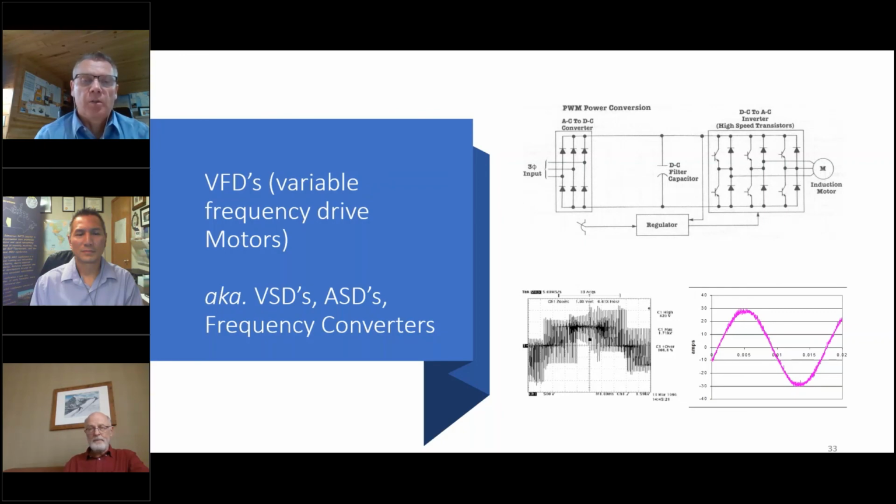And when you energize a motor, it's going to lift up from its stationary position and find its optimal place where it's magnetically happy. And on most motors that I'm aware of, in initial setup, there should be an indicator on the driven shaft with a couple of scribe lines.